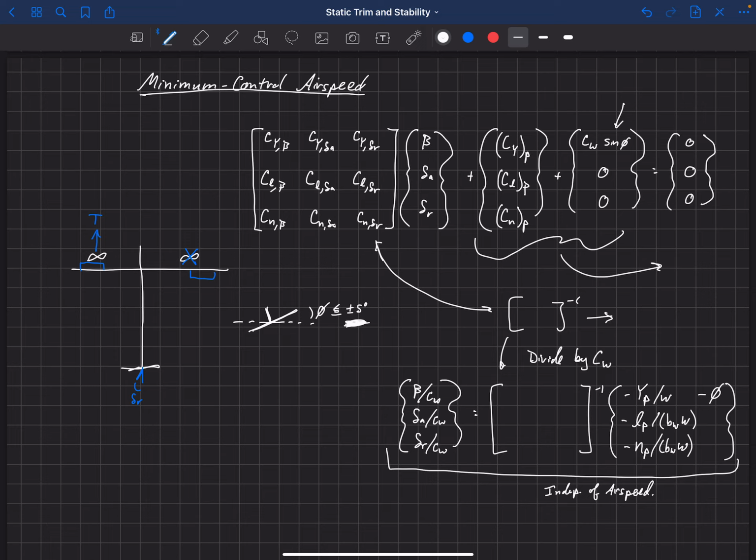So these coefficients inside of this matrix here, these are our control and stability derivatives, and they can be slight functions of Reynolds number. Now at low speeds, we're usually talking about speeds very close to takeoff and landing, and so anyway, we can compute what these would be at those velocities.